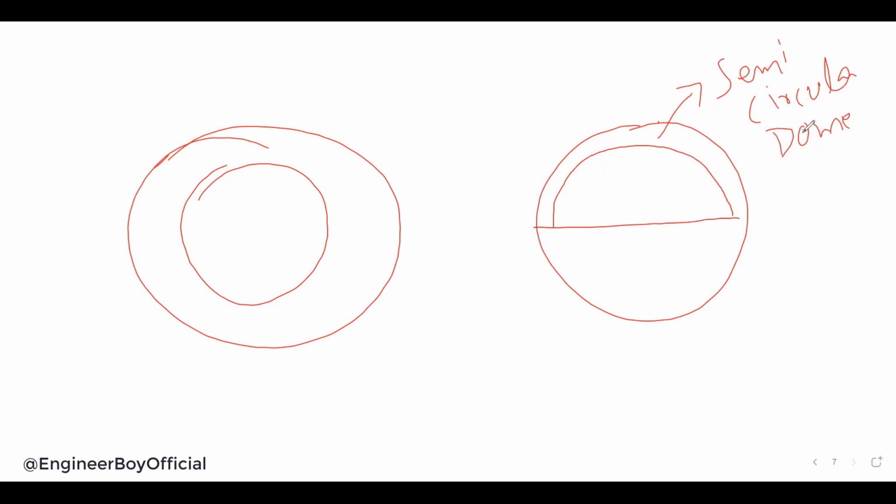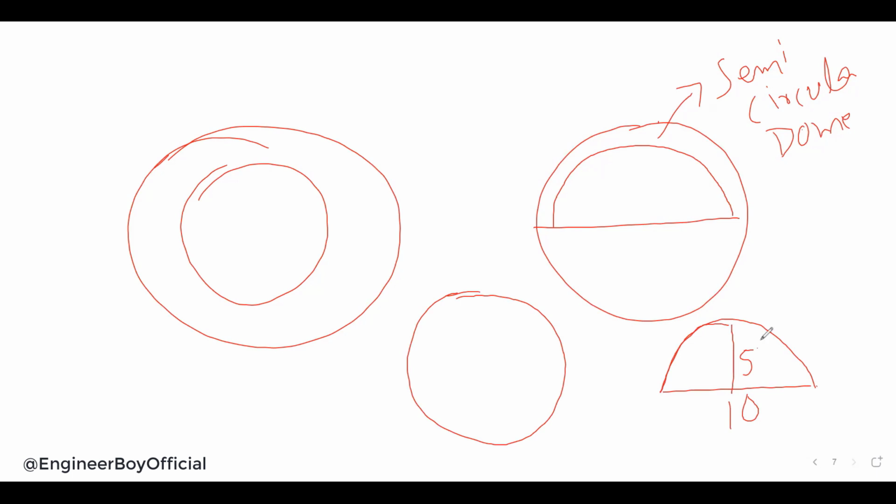Most of the students don't understand it. For a semicircle, you have to look at the chord. Let's say I have some dome like this, and this is 10, the chord, and then the rise, let's say this is 5. How can I confirm if it's semicircular or segmental? As you can see, this is 5 units. This can be the radius. It's simple.